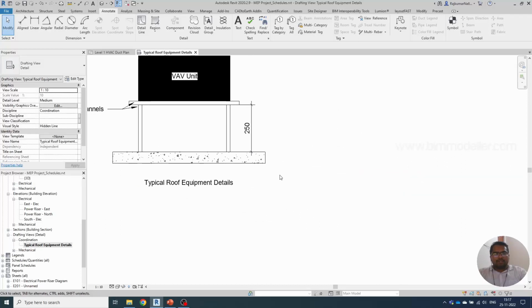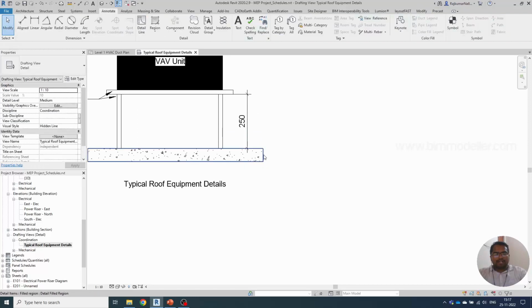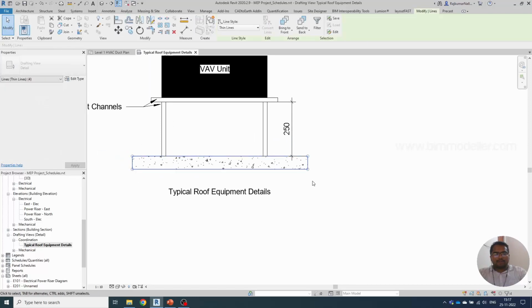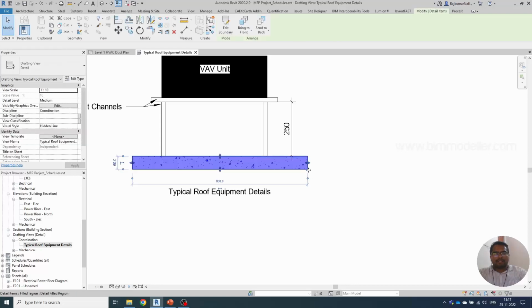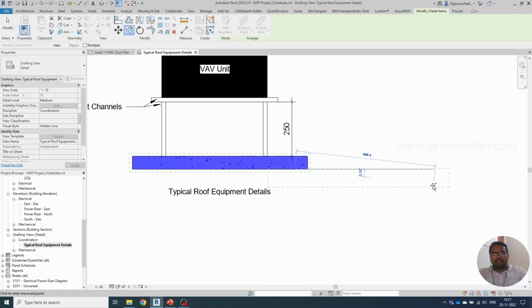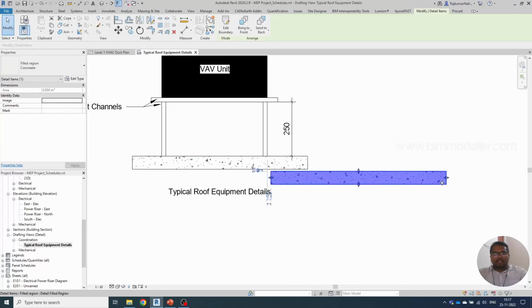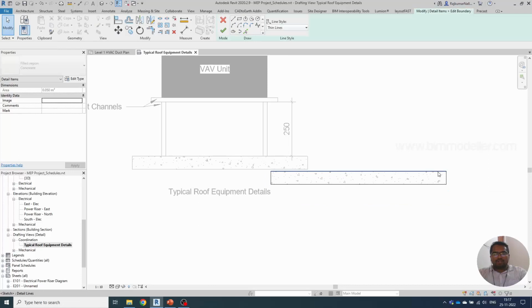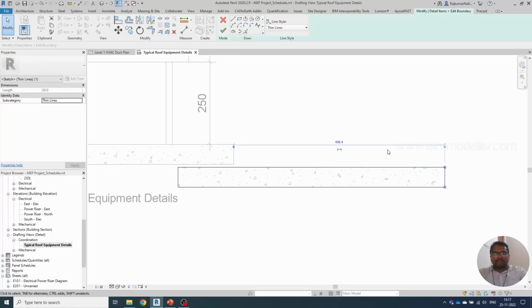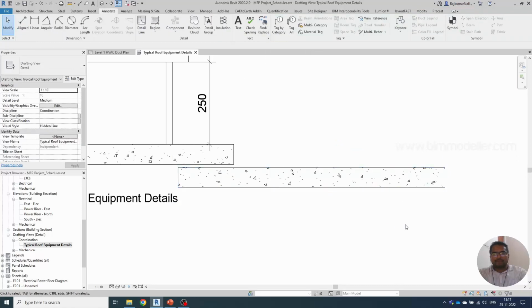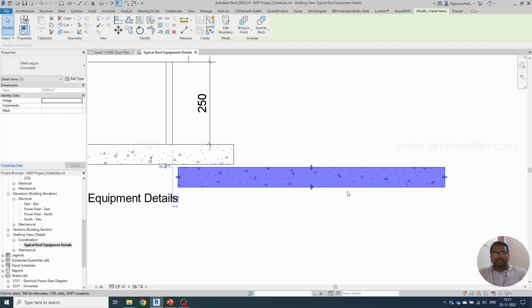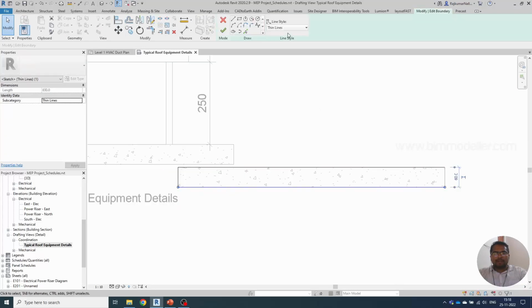Another important thing is that when you have a hatch pattern, underneath it you have other lines which we may not need. It is necessary to make a copy. I need to explain that each hatch pattern will have boundary lines like in AutoCAD, and you will be able to change their type, so you can make them invisible as well. Finish it. Now you see that your hatch pattern will not have the right side boundary line. The lines will be there, but they are invisible in the view. So there is a line style called invisible, and you can use it when you need it.